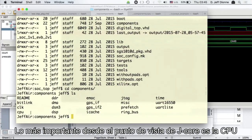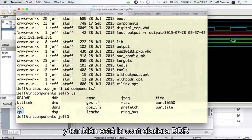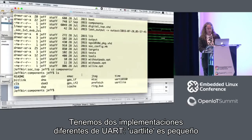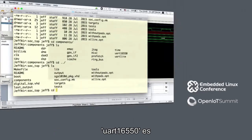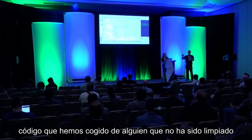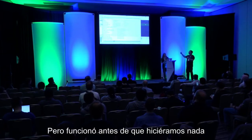And the most important thing from a jcore point of view is the CPU. But we also have, for instance, the caches. And there's the DDR controller, the DMA engine, and all of that. So this is a mix of the open and the closed. We have two different UART implementations. UART Lite is tiny. UART 16550A is existing code we got from somewhere else that hasn't been cleaned up into this proper object-oriented VHDL format, but it worked before we did UART Lite.